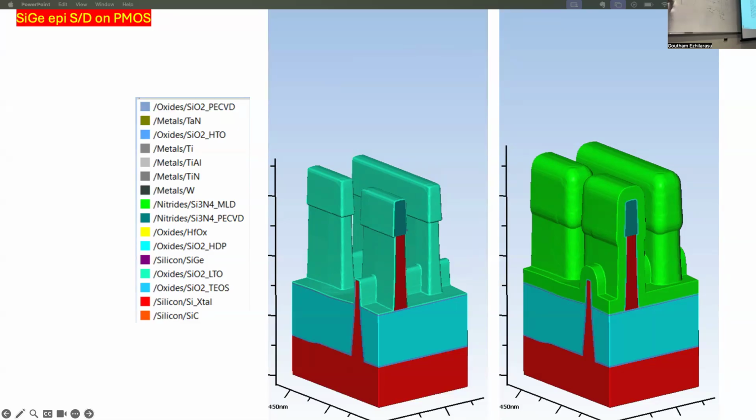But remember how you create the strain engineering for the bulk MOS, right? So first, you create a lightly doped region. And then you create the sidewall spacer. And then you etch the silicon down like this. But you do basically a wet etch, so you do a crystal etch. And then you epitaxially grow your silicon germanium, something like this, right?